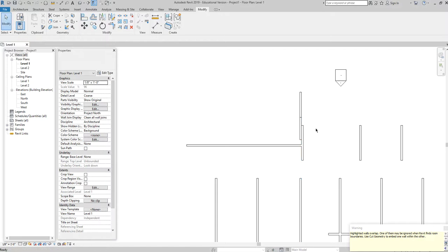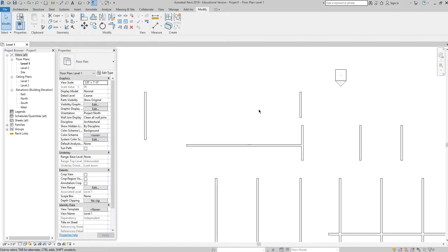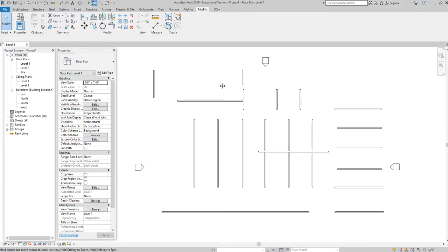I'm going to hit escape. Okay, but really, I'm going to hit Control Z to undo that. The idea behind align is once you've drawn some geometry, right? I talked about how not most of the time, but some of the times I don't get everything quite precisely drawn, right? I get things mostly there and then I have to alter them to get them perfect, right? And so this is one of the commands that will help me do that. I can get things mostly correct and then I can use align to align them to other objects or things that will make them the right dimension, okay?